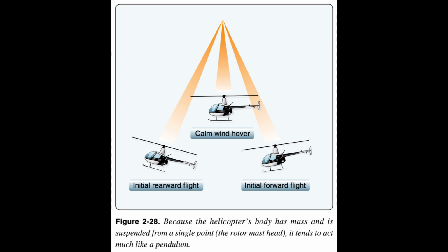End of page 2-15. When rearward flight ground speed equals the wind speed, then the helicopter is merely hovering in a no-wind condition. However, rearward hovering into the wind requires considerable care and caution to prevent tail strikes.